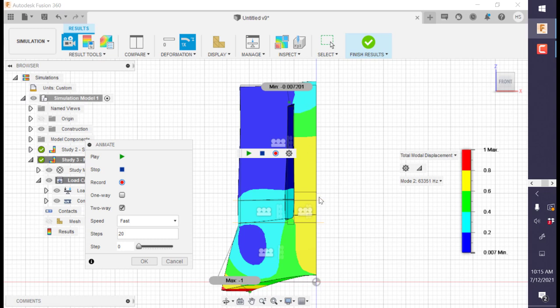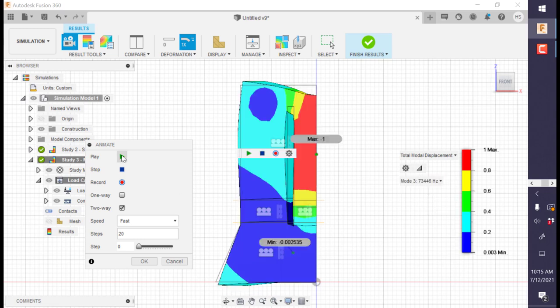For example, this is much more sensitive to the center bolt. If you want to investigate properties of the center bolt in our transducer, we can identify a mode of vibration, a mode of resonance, which is more sensitive to that specific component. If you're doing some type of specific analysis, which is very common. Here's another resonant mode